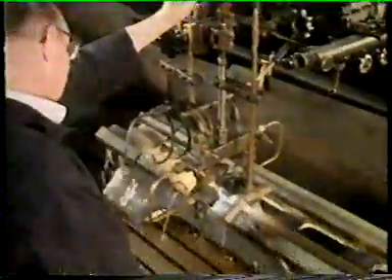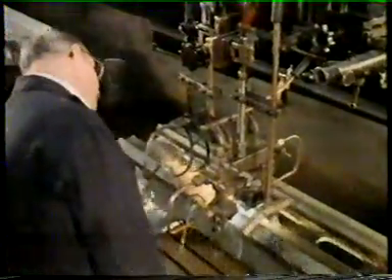Here we're machining one of the slideways. Now, in service, this part needs to resist wear and indentation. It must be hard, but in its present state, it's relatively soft, so now the slideway must be hardened. We do this by heating and then cooling the material in a carefully controlled way.